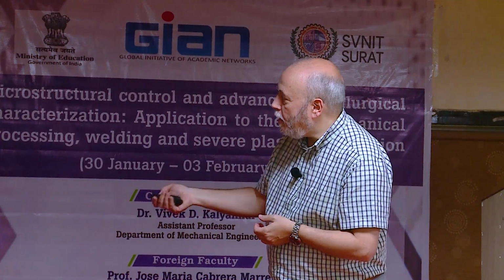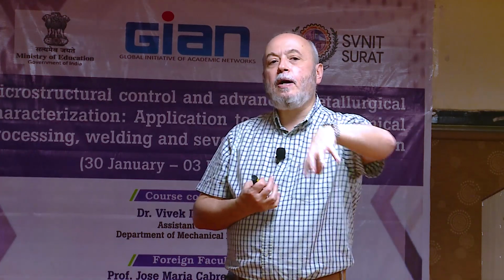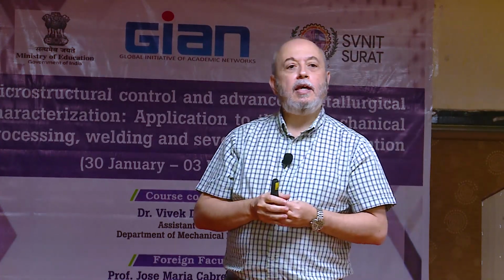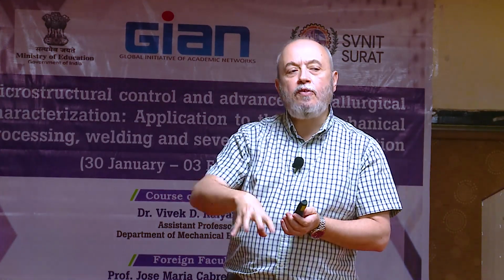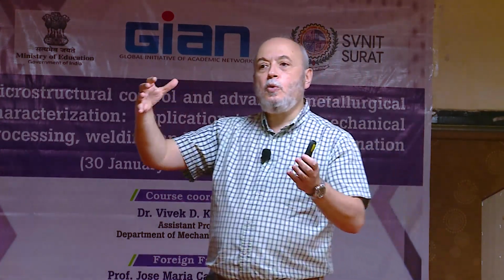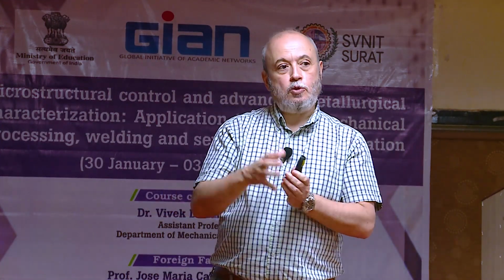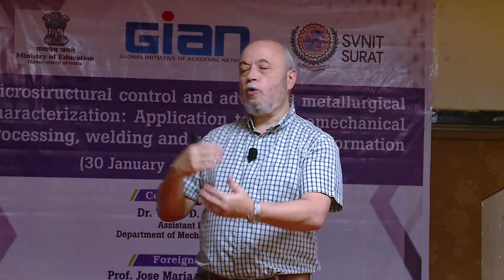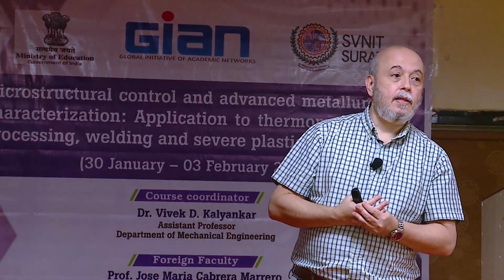Another process available today is the so-called metal injection molding. You mix metallic powder with polymer, and then you inject this mix into a mold. When the process finishes, at the binding system, you evaporate the polymer, and then you get a metal, which is basically powder, that you have to sinter. So here you are mixing the good things of sintering with the good things of injection molding in polymers, okay, or injection metal casting.